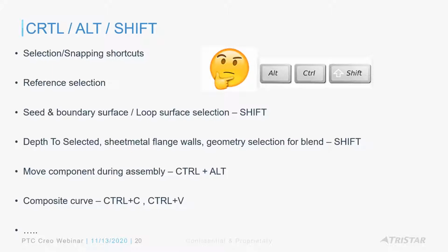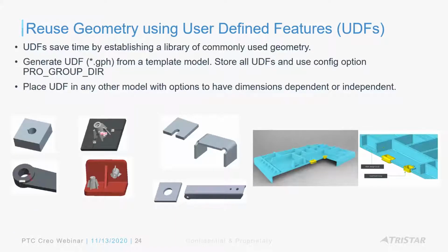That's the key. And we talked about how in the sketch also, this makes a difference, right? Holding down the Shift doesn't auto constrain, or it doesn't assume constraints. Temporarily, you're almost like removing the intent manager, temporarily while sketching.